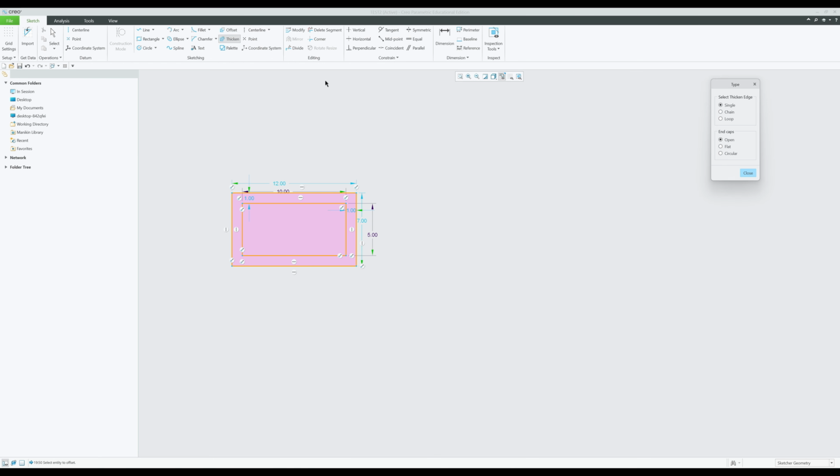Okay, so the next option is loop flat. It's also similar to the open one. I'll just show you how it can be done. I'll take a different shape. So take an ellipse, say thicken loop flat, select it, say 1 and 1. So you can see it looped outside.